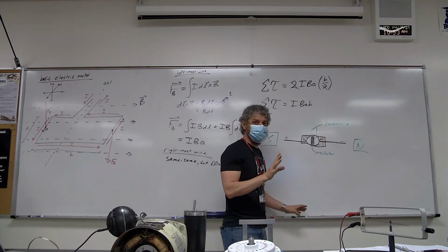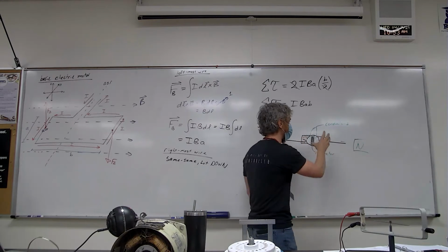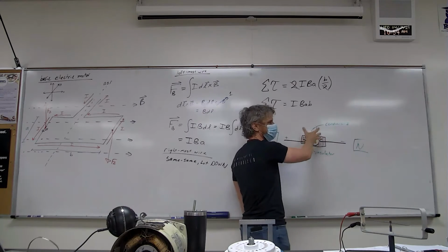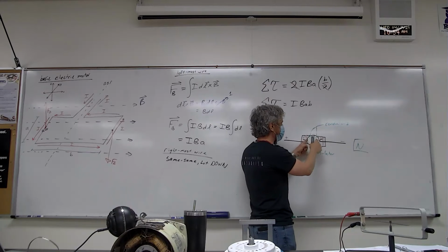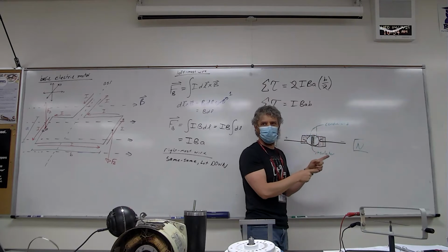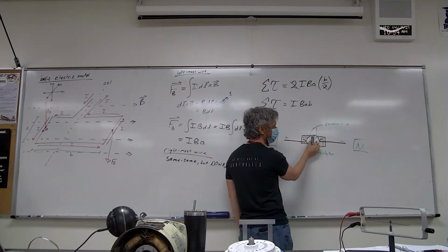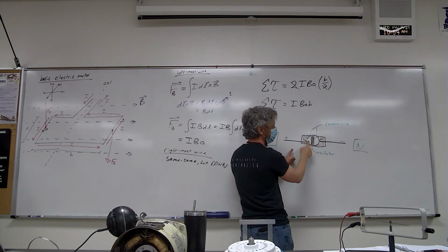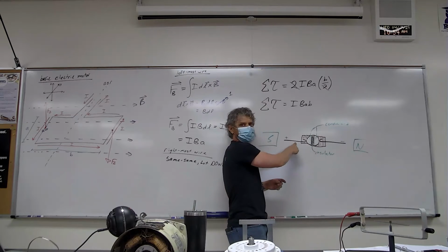But again, if there was no fancy shenanigans going on here, this thing would rotate and then it would stop, or it would pass through it and then wobble back and forth. What this thing does is reverse the direction of the current in the coil automatically. When this thimble and the wires attached to it rotate through 180 degrees, this one then gets in contact with this brush, and this one gets in contact with this brush.